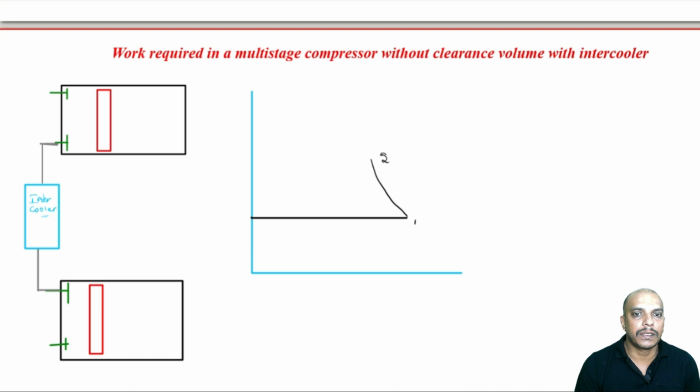Now in the last case, this was directly fed into the second cylinder. Now let us cool it before we go for compression. Now why do we cool this? It is very important that we are trying to compress a fluid, a gas. Now in the process, if the pressure is high, in the process of compression, pressure becomes higher, and as the pressure increases, temperature also increases.